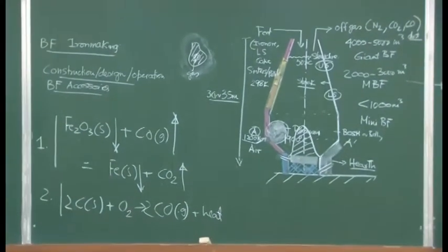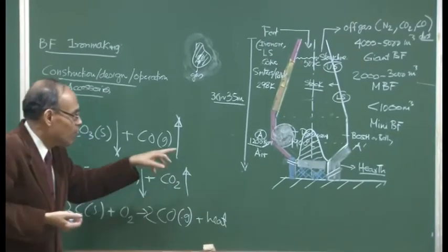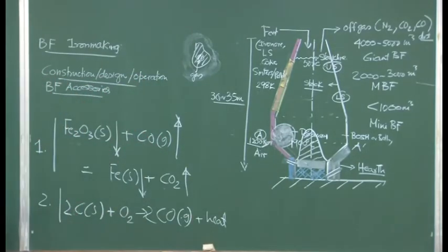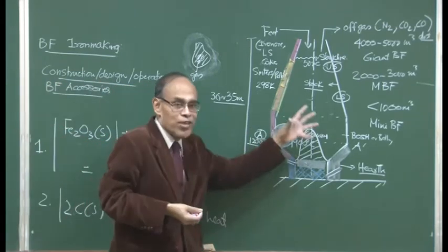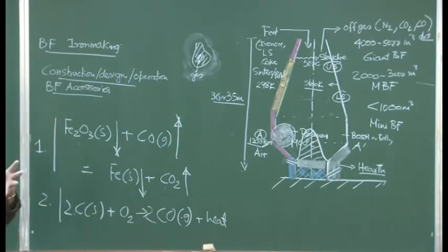But we will see that we can blend a little bit of hydrogen through the tuyere into the system, and we will see why that can increase the reduction efficiency in the furnace. But if you try to inject too much hydrogen inside the blast furnace, then the blast furnace becomes cold, and the entire reaction, or the system of iron making, collapses in the furnace.